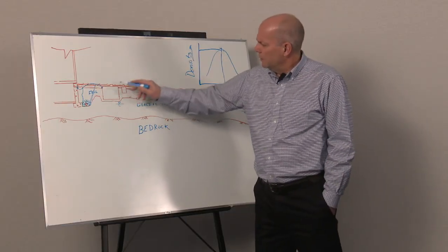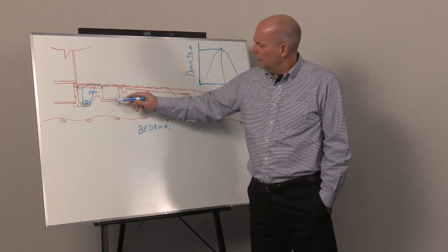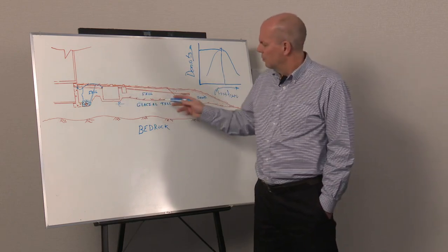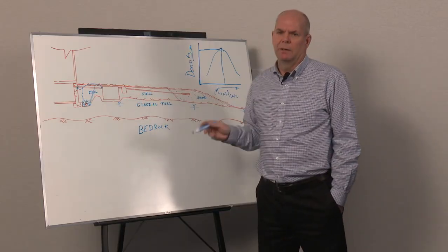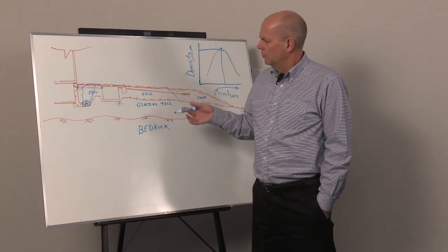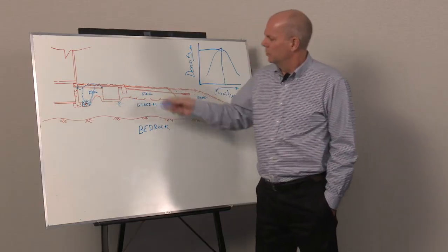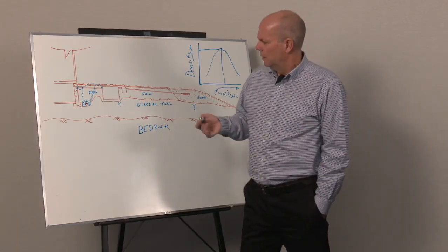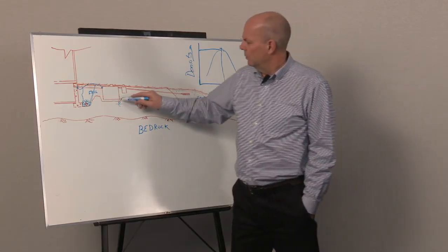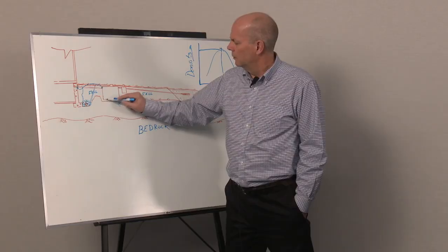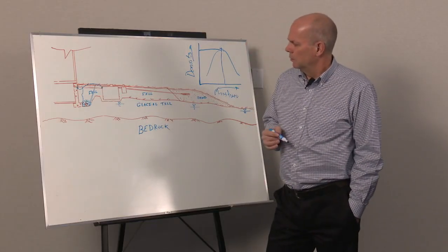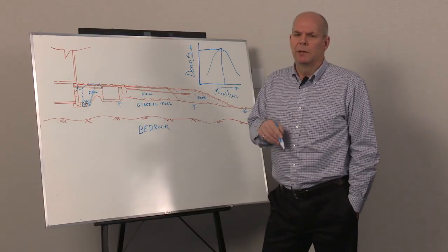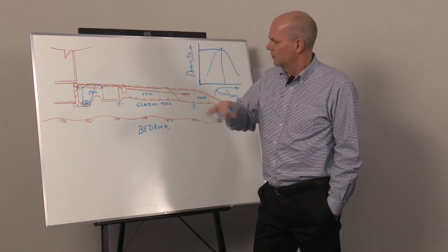When you're excavating for these tanks, like I was saying, if you're deep enough and there's not much fill, the tank's probably going to be founded on the glacial till. There's no reason you should have problems with something founded on that material, provided you don't let it get too disturbed when you're working on the base. You clean it out, you tighten up the surface, put in whatever leveling course you need under the tank, and it should be pretty straightforward. If you over excavate, regrade loose material without compacting it, you can get some settlement of the tank.